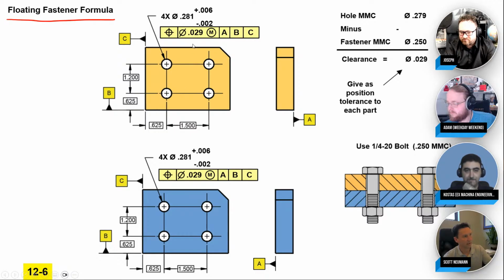So how do we assign the tolerance for this? Well, easy datums on this one again. Just those edge datums. Again, hopefully they're functional, and that's for another video on picking functional datum features. We have basic dimensions. I'm going to do inches this time. So 1.5 inches, .625, .625, 1.2 inches. And then the same thing on the other part, they pretty much match. You've got A, B, C, and all the dimensions are lined up perfectly in the LibreCAD system there.